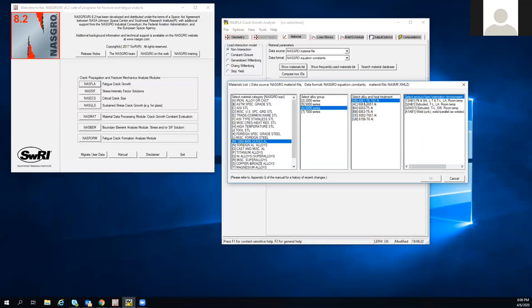If you know the material is 6061 T6 and you're sure that's the heat treatment, then you're in the right ballpark. But from here, you can see really closely that the first one is a plate or a sheet, where you have LT or TL, longitudinal transverse or transverse longitudinal, and lab air room temperature, versus something that's extruded. And you see these different extrusion directions. This one is also a weld. So these will change the parameters that you're looking at.